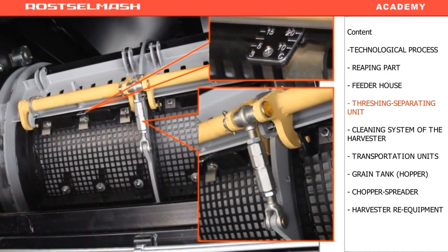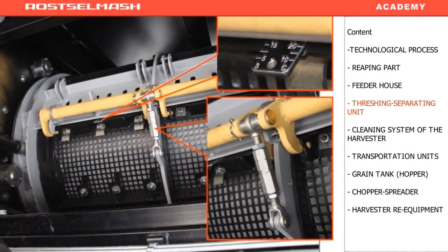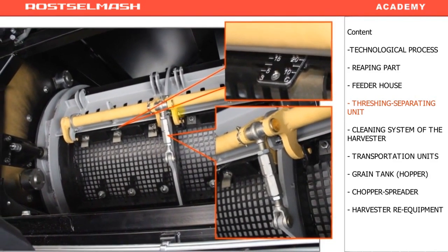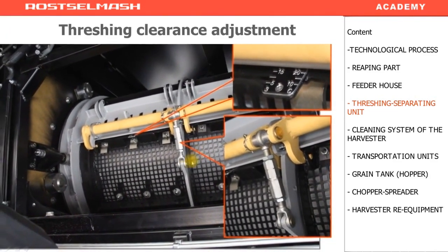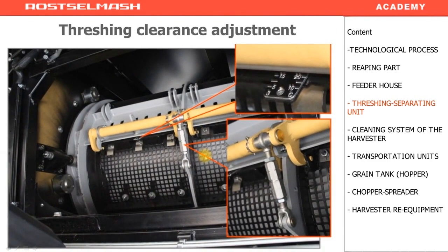After adjusting the clearance, don't forget to tighten the nuts. Repeat the same procedure twice, for 2 pairs of decks. To do this, we move the concave rotation behind the reduction gear. Before doing this, take off the belt, rotate it to the next pair, adjust it, rotate to the next one, and adjust it. The clearance must be similar in all the 3 points.